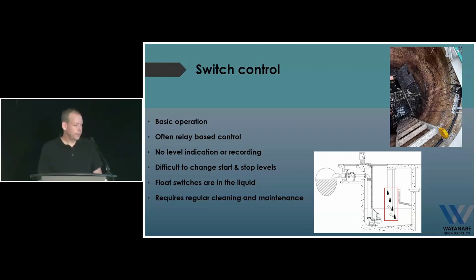And part of the problem with this is, as we know, this isn't clean water, so there's a lot of stuff hanging around in there, tends to get jammed up on the floats. If you've got any grease problems, it builds up on the float switches. And recently I was actually at a community where they were having some issues with a pump, and the reason was that their float switch was actually jammed to the sidewall of the wet well in the grease, and it was permanently tipped, so the thing was running 100% of the time. So that was a little bit of a challenge. We got that cleaned up.